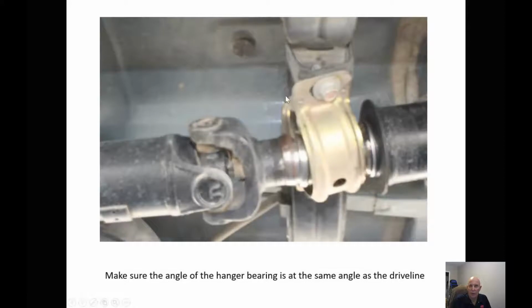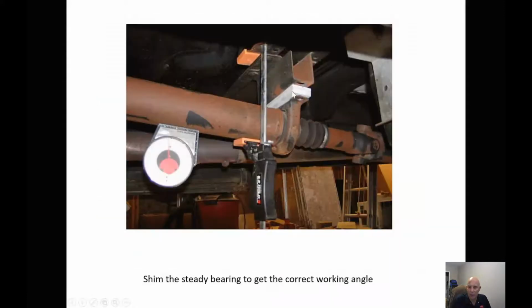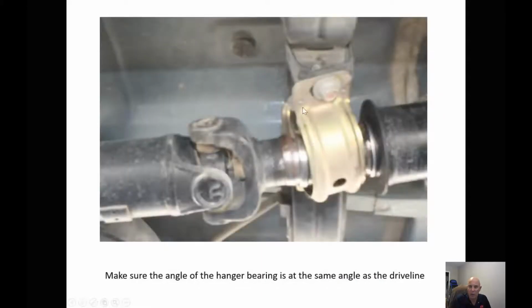The other thing we want to look at is the angle of the driveline. If you take a look at this one here, how nice and straight it is, well, this one has an angle to the hanger. So we have to make sure that when we put this back together again, the angle is close. Otherwise, the rubber for the steady bearing is going to eventually work its way out, and we're going to have a failure.